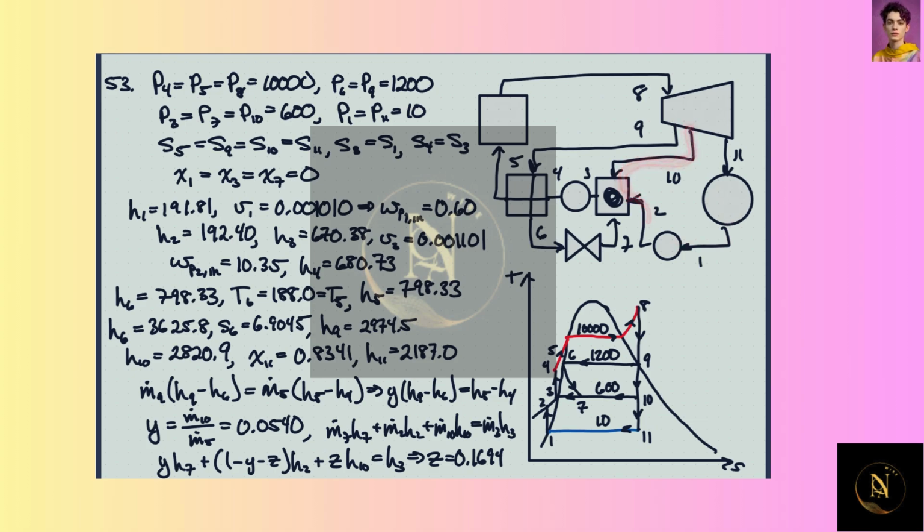the pressure coming down from 10. So the pressure at 2 and at 10 are going to be the same, and the pressure at 3 and 2, and then, well, here we have another pump. So then we're mixing here. We're mixing steam from the turbine, feed water, and then the steam from the turbine that has been cooled in